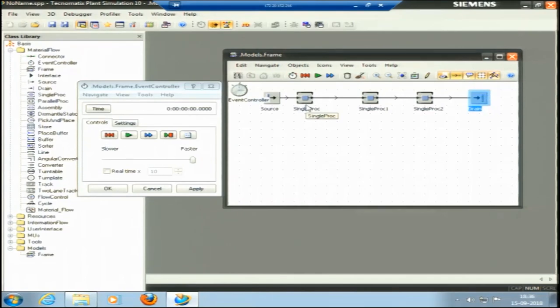If we talk about plant layout, this is work study: what is the minimum space that has to be kept? In manufacturing, other than the width of the machine, the space between two machines is generally kept from 0.8 meter or even more, so that the workers can move in between. This is a space in between. I have just kept it at a random location here.